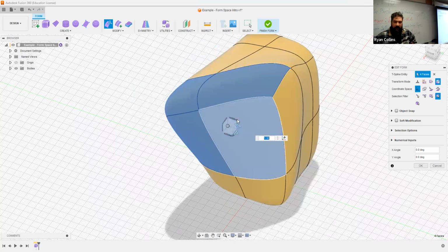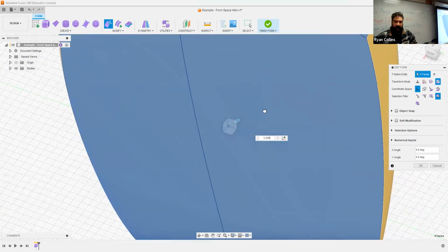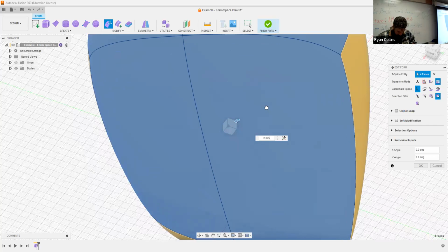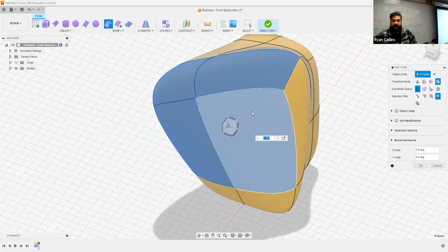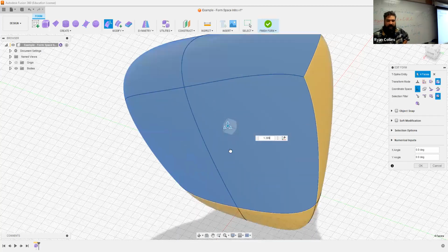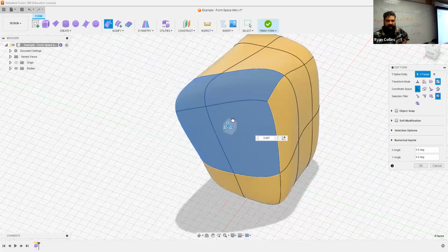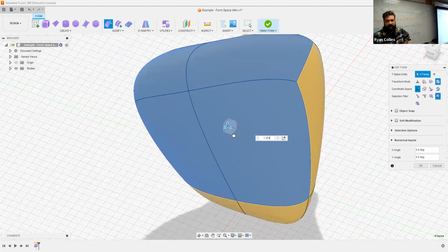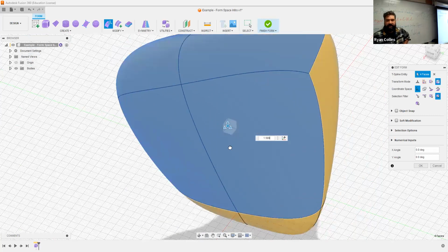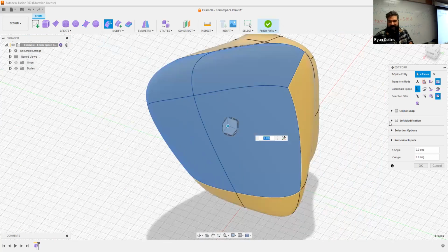Non-uniform scales. However, if I select the curve, it moves in both X and Y. Or sorry, in this case, it's both Y and Z. To do uniform scale, mouse over the center, and you see the three triangles appear on all sides of that circle. That is my uniform scale. Again, it functions off of numerals, so between 0 and 1, 1 is the current scale, 0 is less, and then multiples beyond that. So there you go. That's scale.